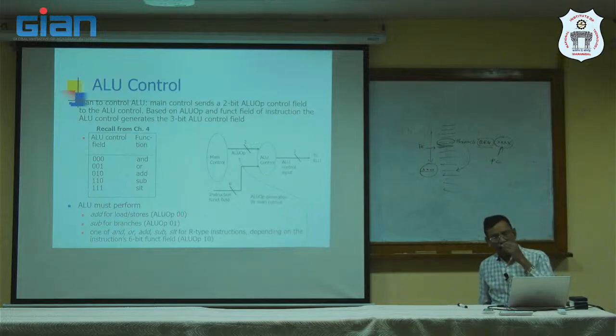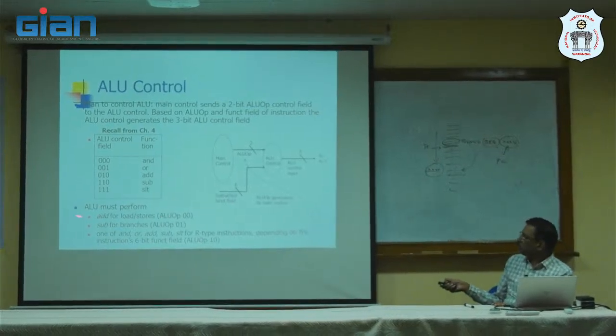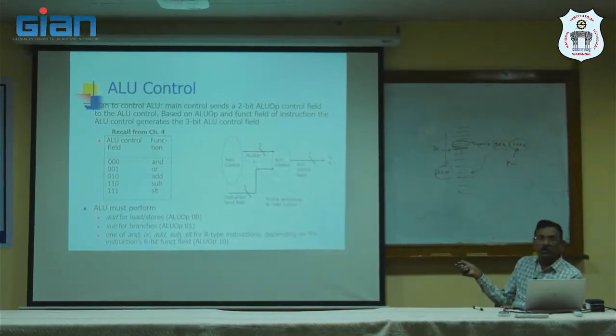That means the load operation and store operation, which is instruction address calculation. So for load word, store word, the add operation, the ALUOP 2 bits are 00.